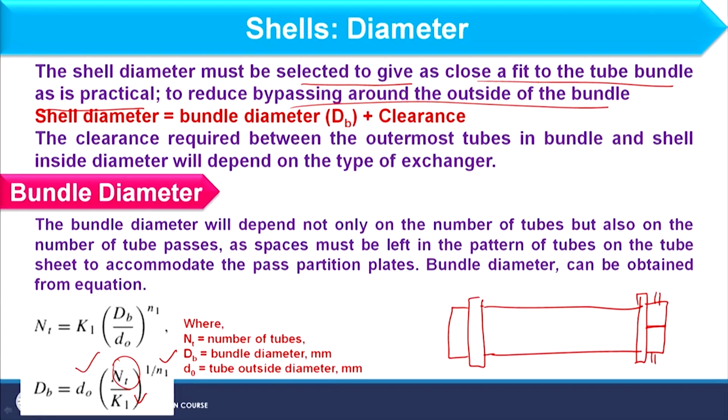And the reason is, when I am dividing this tube side flow, I am dividing the number of tubes in these two manners. Okay, in these two sections. So what will happen? Whatever plate is available, just corresponding to that side in tube, tubes will be available like this and like this. Okay. So this is one tube, this is another tube.